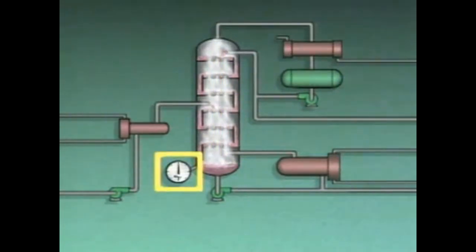By lowering the temperature at the bottom of the column to its proper value, the overfractionation problem can be eliminated, and the column can return to its original operating conditions. In this topic, we focused on reboiler-related problems, and we described an efficiency problem called overfractionation.